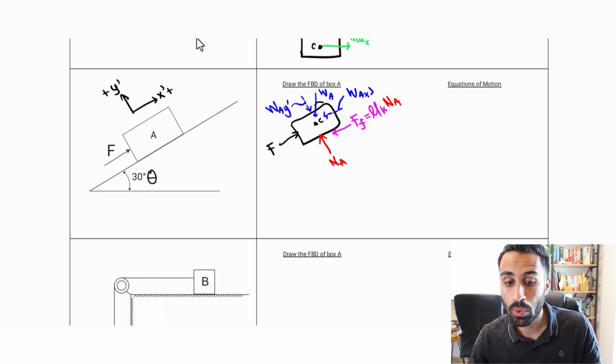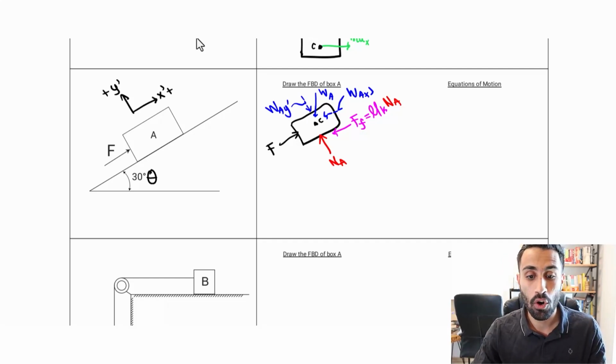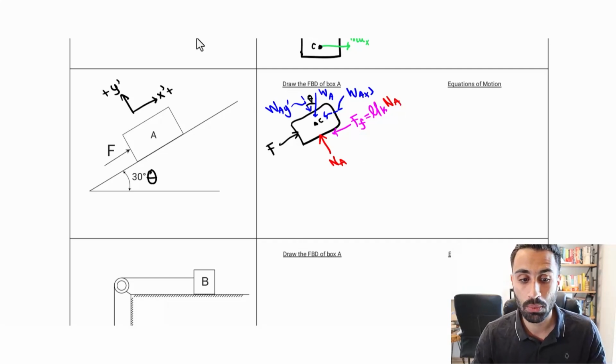Where's theta here? Are we going to put it there or there? Where do you put theta? Here or there? Always with the y component. Theta's right there, so that 30 degrees should be there. We talked about that under the statics, I won't go through that. Just know it's always with that y component. That's very important as we continue because we're using this sign convention.